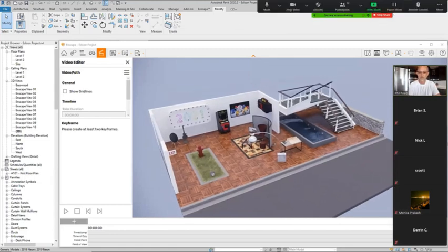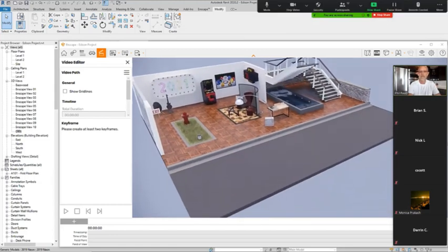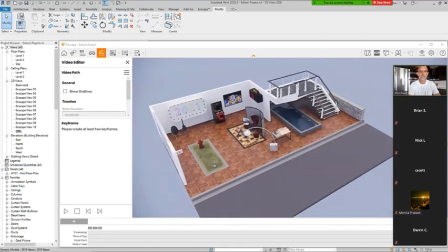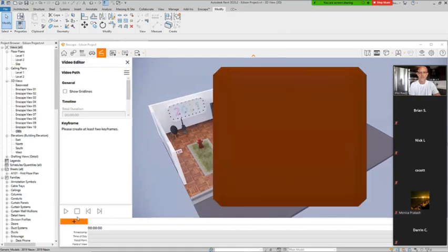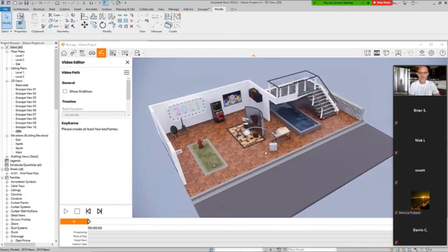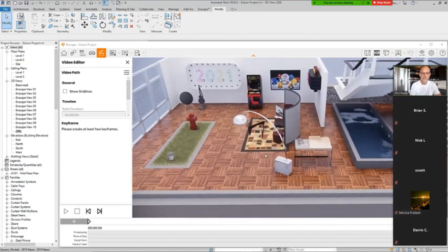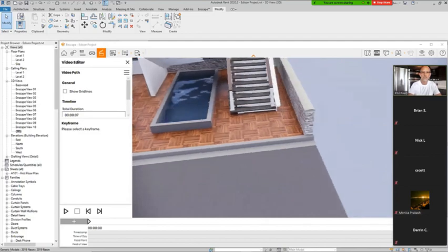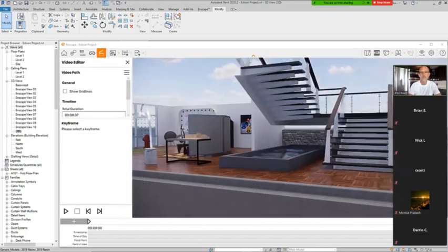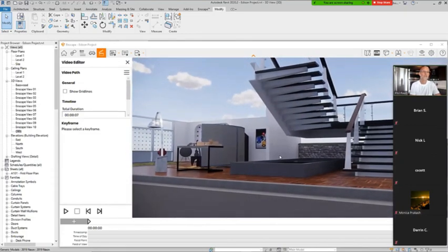So I'm going to start up here. Let me just move up a little bit and maybe point the camera down. So let's say we'll start out here and we'll create a camera. We can do that with this little plus symbol, okay? Then I'm going to start to move down. This is going to be our second location, and I'll place another camera, but this time I'll do it with a K key. And we're still in first person mode. It's not like in Revit where we're in third person mode. And this is going to be our third camera, okay?